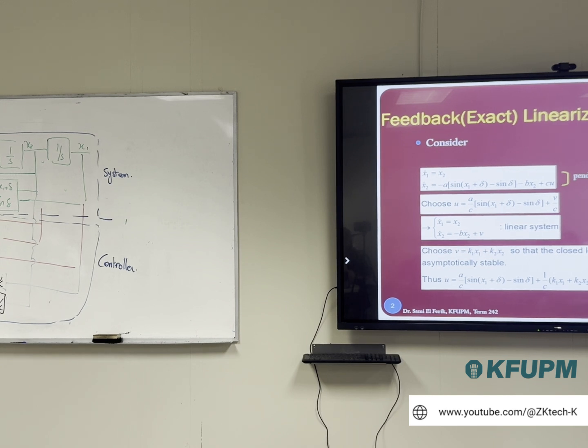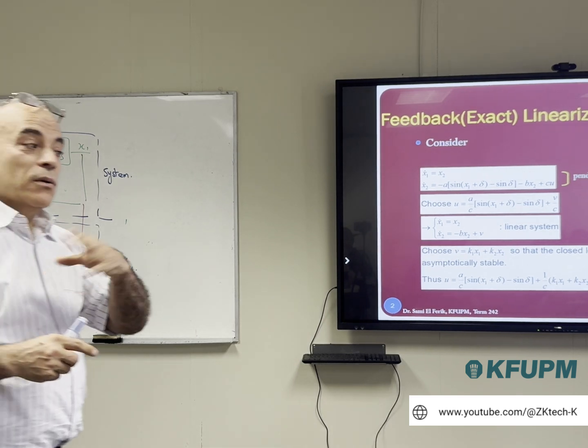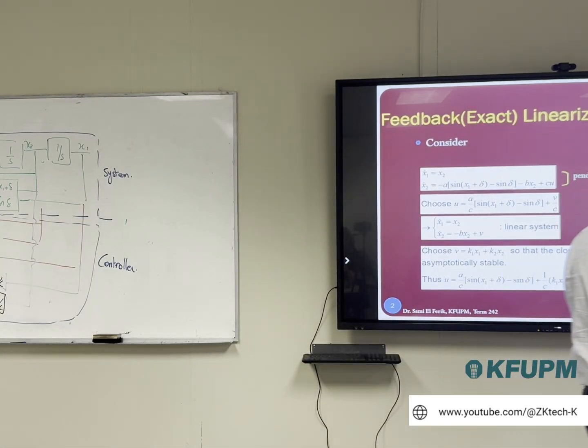What is the advantage? The system becomes completely linear without losing the dynamic. It works for every point. So the model can be extrapolated to any point. We need a fully observable system so this can work? Not necessarily, you can put in an estimator, a state observer, a state estimator. I mean, anything that will allow us to estimate this thing.